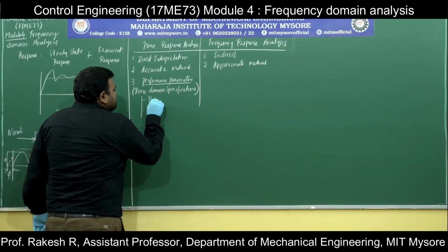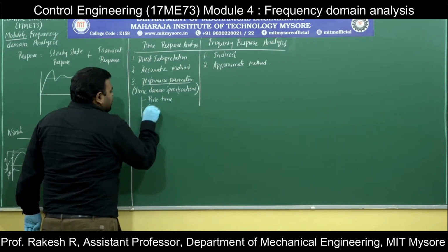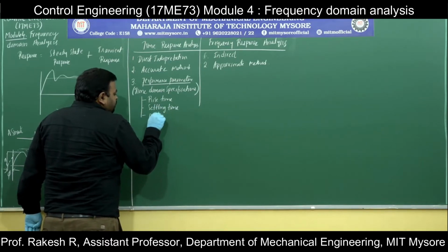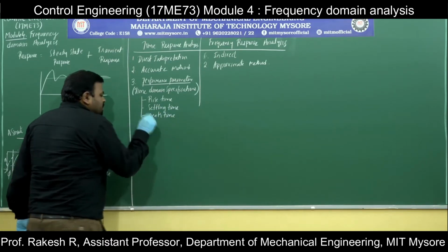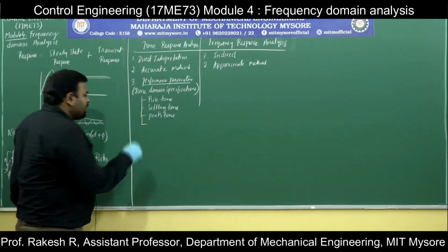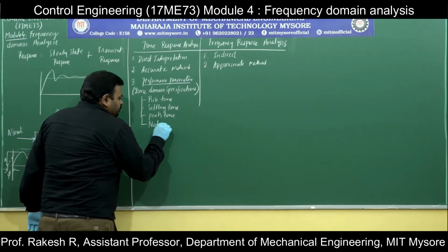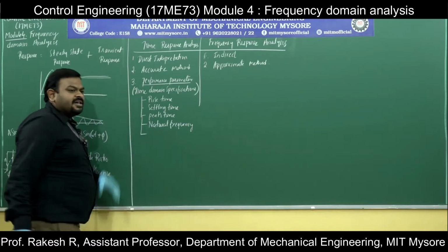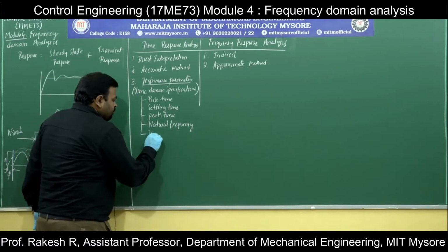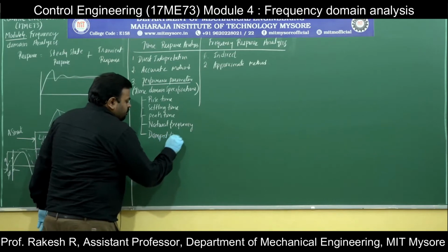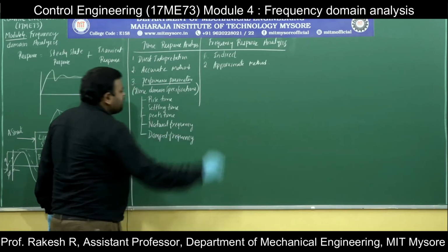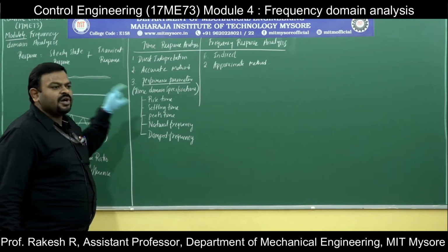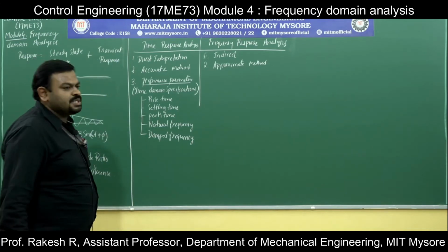Rise time, settling time, peak time. Sometimes we also directly calculate the natural frequency of the system, and also the damped frequency. These are the important time domain specifications, and they are the performance parameters in time response analysis.